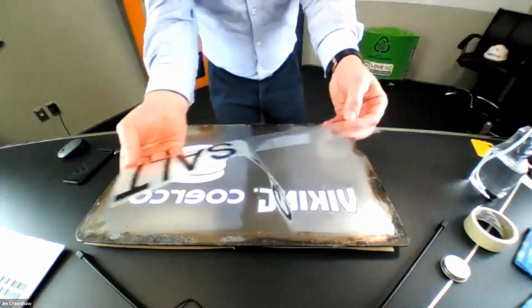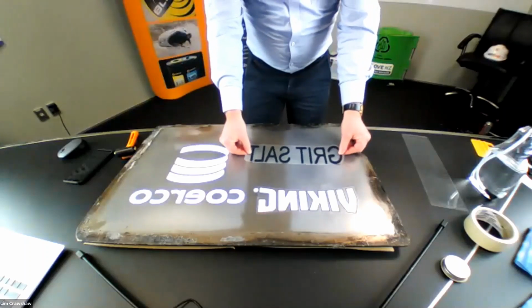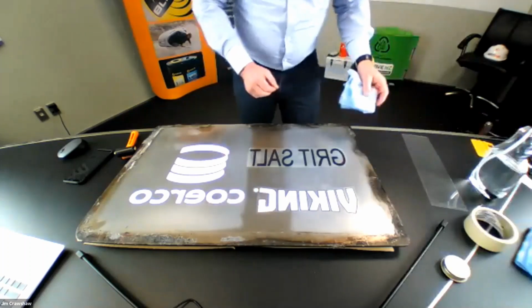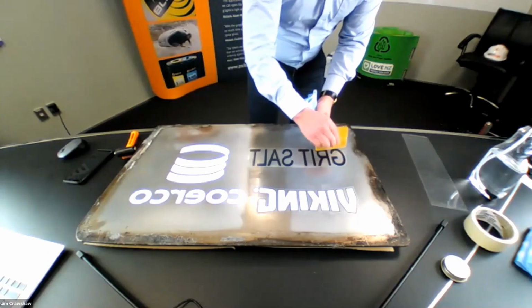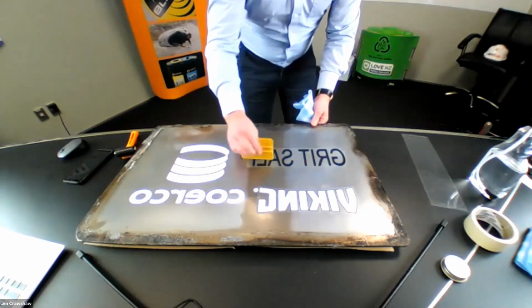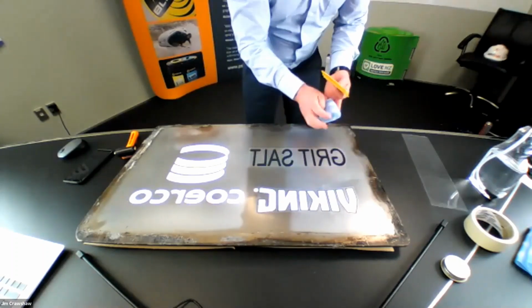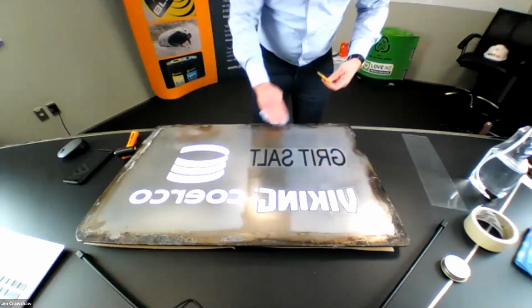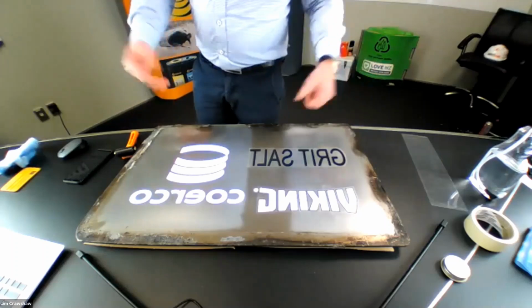And then peeling the graphic off the transfer, and then applying it onto the mold. And you can see here it's slipping around, so the adhesive isn't causing it to stay in one place. And that allows you to align it just perfectly. The other cool factor is that when I squeegee over the graphic, all the air comes out with the water. So it lessens your chances of trapping air bubbles as well. This is a really popular method for users that are using really large graphics that might have a large surface area. I'm just using an absorbent cloth here to clean the water away. So those graphics are ready to go and get molded.